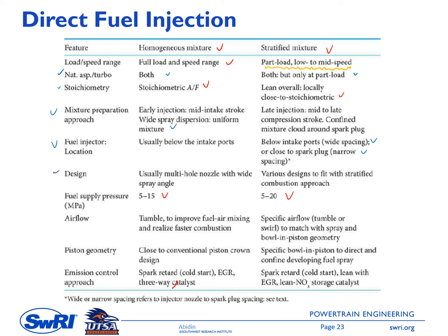Having high injection pressure means we need to put in more energy, and this is parasitic energy because it is used to increase the injection pressure, and it comes from the engine power. As long as the engine power increase can offset or exceed the injection pressure energy, then it is good. It means we can gain some engine efficiency due to the higher fuel injection pressure.